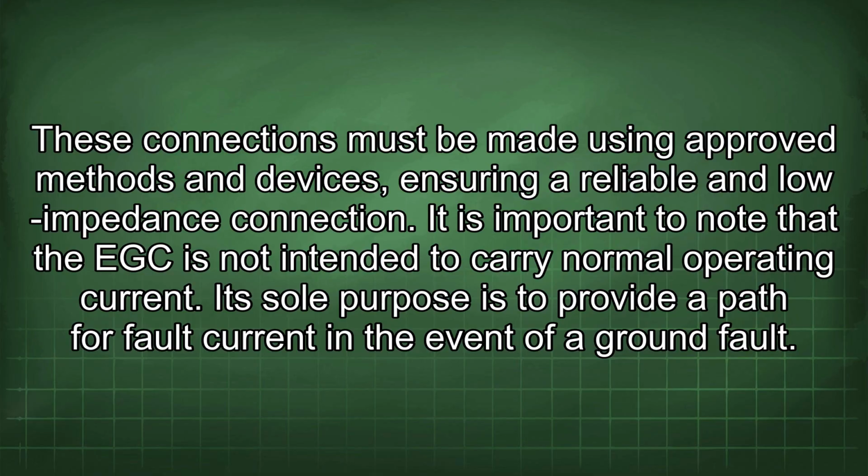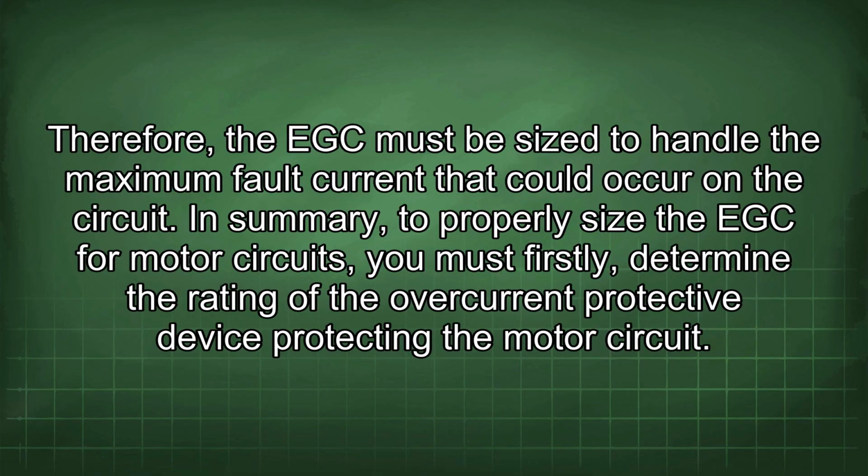It is important to note that the EGC is not intended to carry normal operating current. Its sole purpose is to provide a path for fault current in the event of a ground fault. Therefore, the EGC must be sized to handle the maximum fault current that could occur on the circuit.